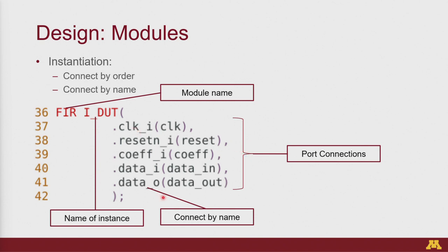So this is about instantiation, and even though it's not shown here, like I mentioned before, when you instantiate this design, you could override the parameters. There's a particular syntax which you can easily Google online to see how to override parameters during instantiation. Essentially I could create two instances of the same module with just different parameters.